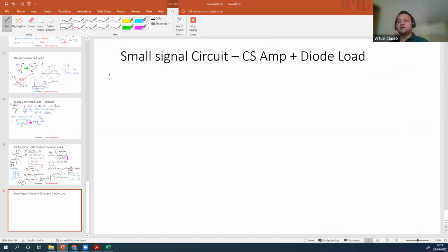Till now we have done DC. Now if you do AC, you've got two NMOS devices, source load. So here you will remove the DC load, put only the AC load. This is Vi. And here there is diode connected, and this will stay diode connected. The VDD can now be grounded. And here is your Vout of t.